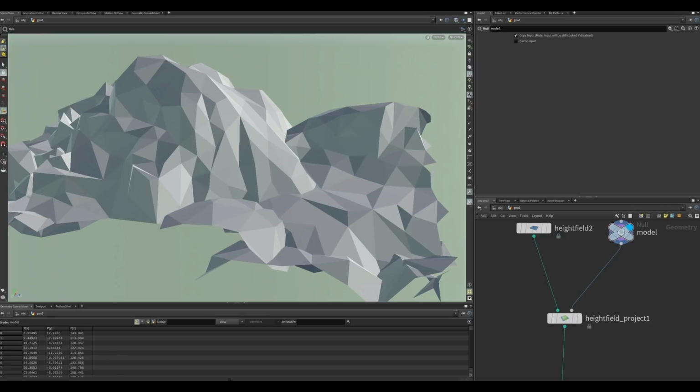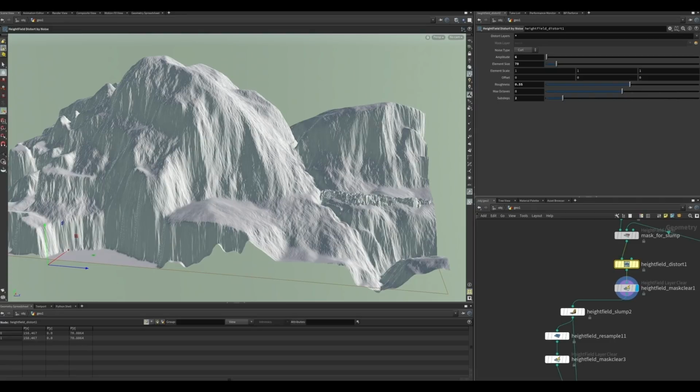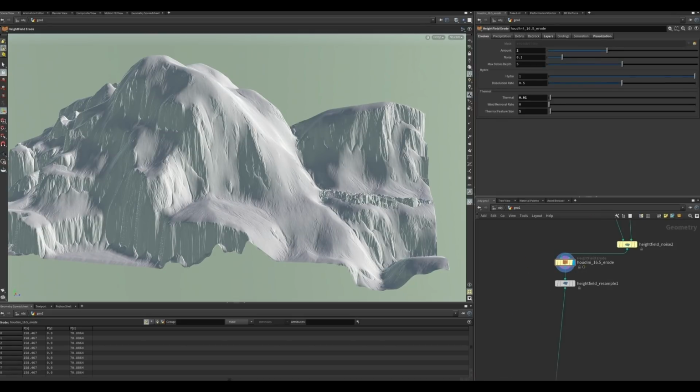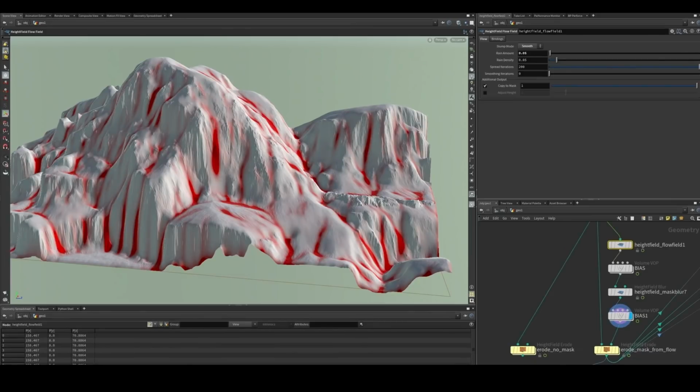Basically, we can take a mishmash of meshes that the art director has maybe put together himself and then just project that to a height field. Once that's projected into a height field, we can add some initial surface distortion, and then run the erosion and slump and emulate all the loose materials and all of that kind of stuff. And then maybe add some more surface noise and more erosion. Then we can generate masks to isolate specific places based off of the actual angle of the slope, or hand paint any of this stuff in.